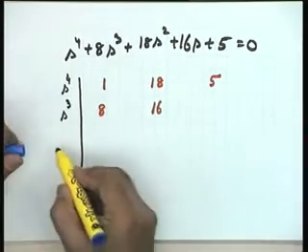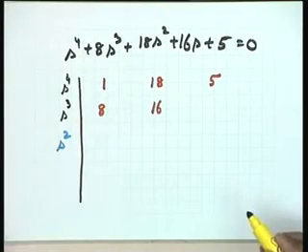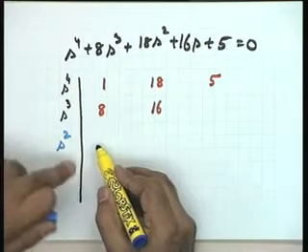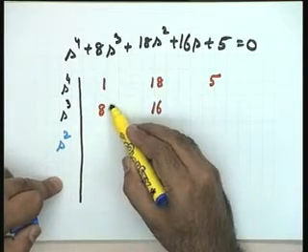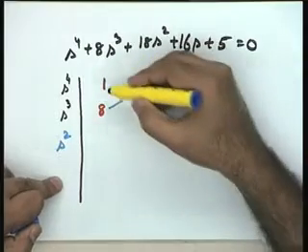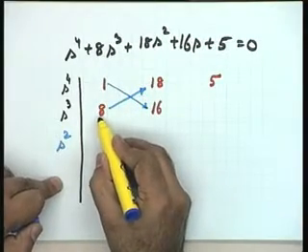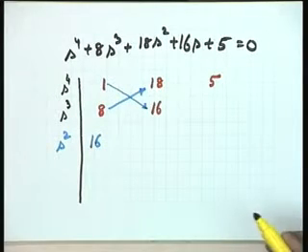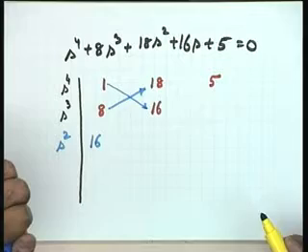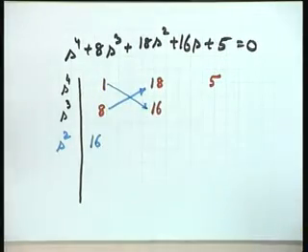Now I will not look at the original characteristic equation. I will now construct the row s to the power of 2, the next row in the descending order. The first element of the row will become 8 into 18 minus 1 into 16, divided by 8. I have got the answer with me, it is 16. You could check please if there is an error. 8 into 18 minus 1 into 16 divided by 8. So I get this as the coefficient.